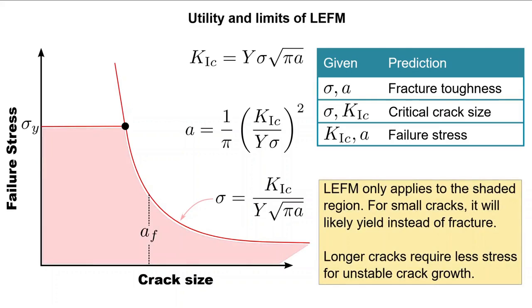The reality is that the longer your cracks are, the better your chances are of predicting their behavior with linear elastic fracture mechanics. If the far field stress exceeds the yield stress, then the failure will be most certainly due to plasticity, not fracture. Long cracks and stresses lower than the yield are most viable for linear elastic fracture mechanics to predict failure.